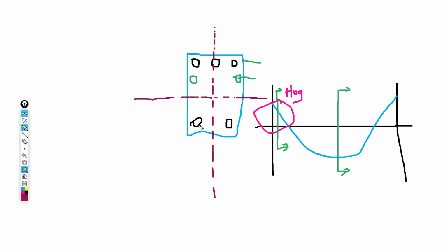But there are scenarios where I find that you need a bar at this point, and also this point. Bars which are placed at the neutral axis, they help in controlling cracks. Those are called side face reinforcements.